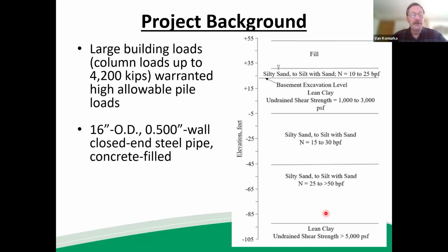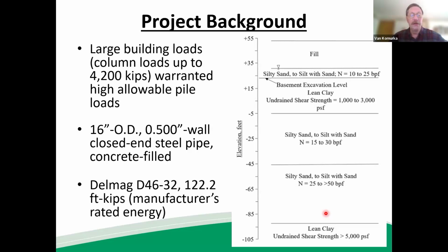So, knowing that, we chose a 16-inch by half-inch steel pipe pile, concrete filled, and we used a Delmag D46 hammer to drive it. The 16-inch pile and this hammer were selected because they were commonly used in the area. The contractors knew how to handle them. They had cranes that could handle them. Nothing exorbitant or out of the ordinary with those selections.